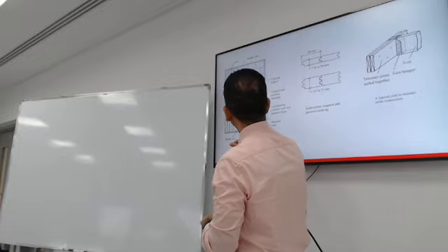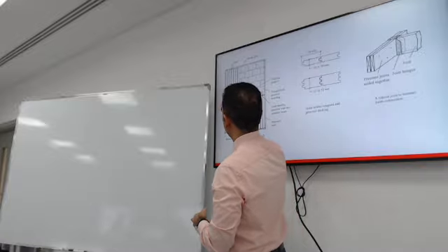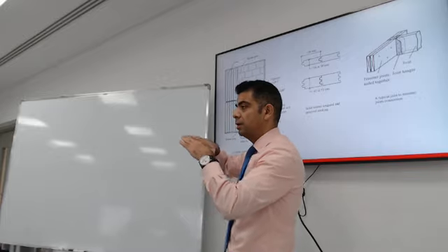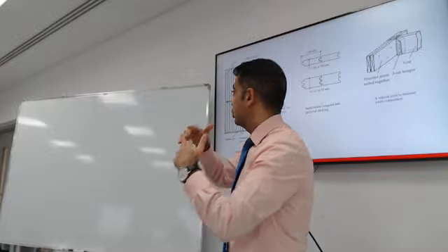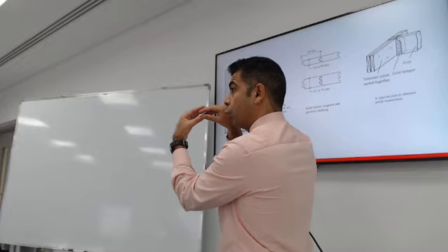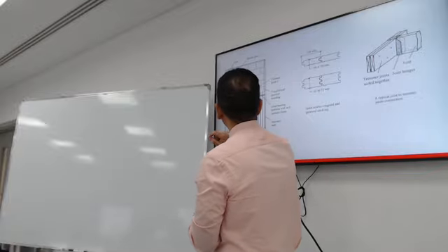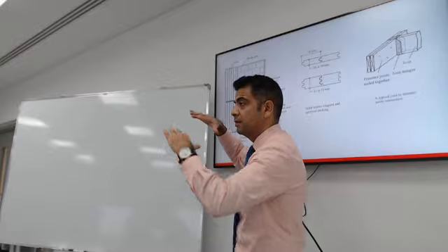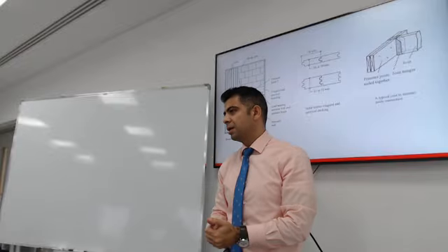You also want to cover up these joists with some sort of boarding, and there are interesting connections that you can have between these boards, like a tongue and groove. It could be a single or double to connect this boarding, this decking, to create the floor, so that you can put finishes and things like that.